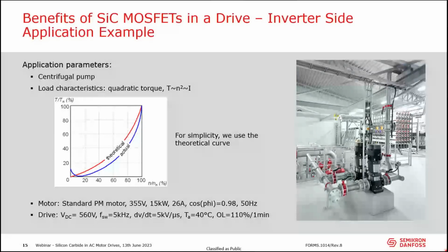When you were reaching the 5 kilovolts per microsecond, did you only change the gate resistors, or did you do anything with the gate capacitance or anything like that? For the simulation, just the resistors. That is all I can adjust. The model in the simulation, of course, considers the gate capacities and all these kinds of things, but I can only adjust it with the resistor. And again, if you have your application, you build it up, then you have to start measuring and go into the details and tune it there. But for simulation purposes, only the gate resistance.